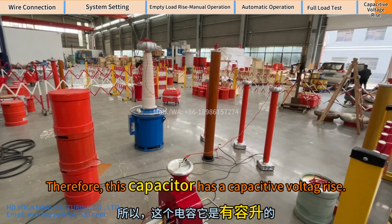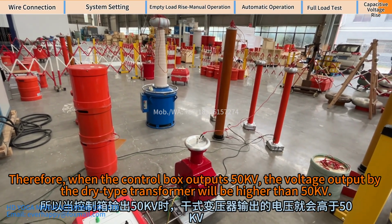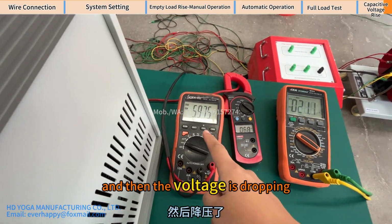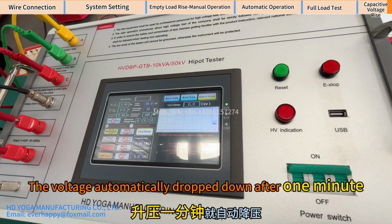Therefore, this capacitor has a capacitive voltage rise. Therefore, when the control box outputs 50 kV, the voltage output by the dry type transformer will be higher than 50 kV. Now we have completed. And then the voltage is dropping. The voltage automatically dropped down after 1 minute.